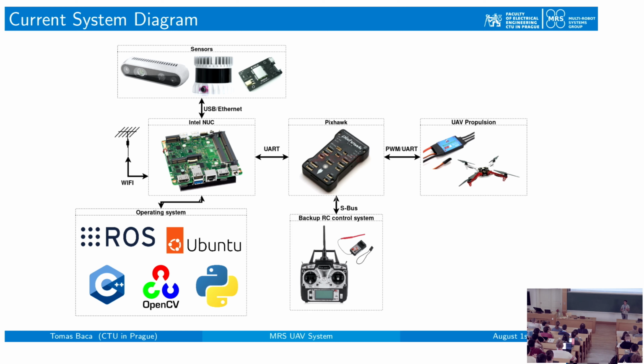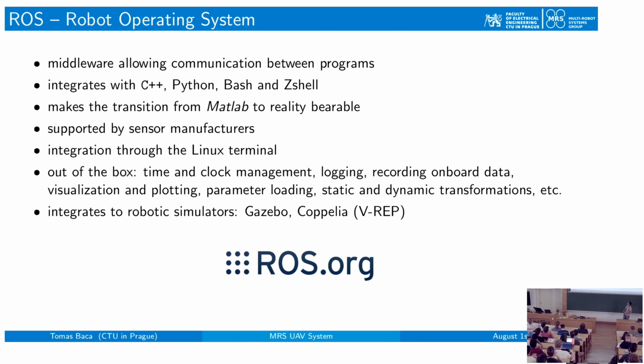And you don't have that much control of what happens inside because there is a lot of stuff running inside which you just can't control. So it's important to still keep in mind that you should not overuse the computer. Still, every time you need some breathing space, some free CPU, free memory, otherwise the drone will crash.